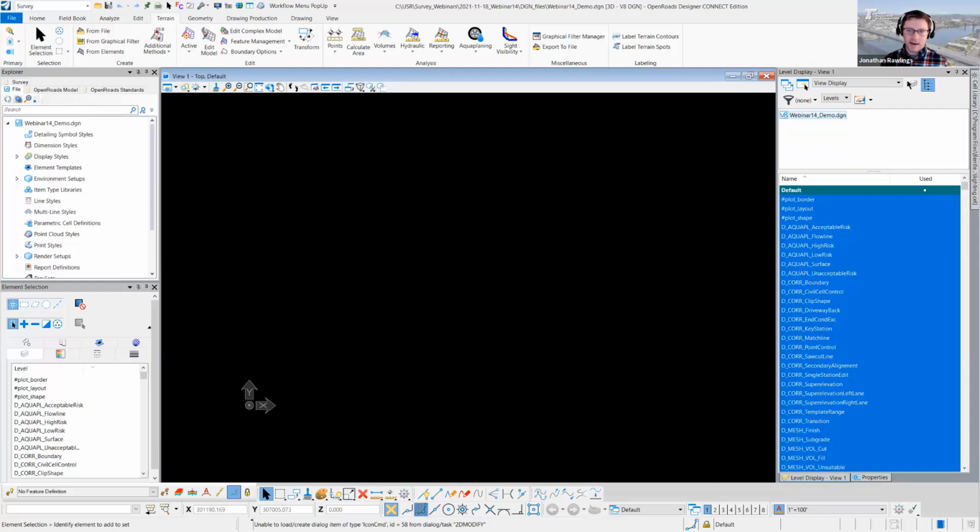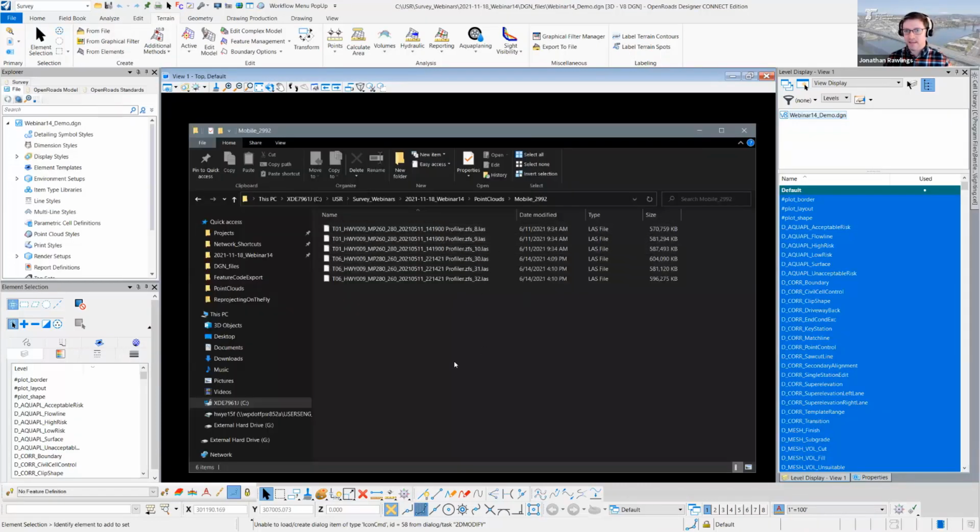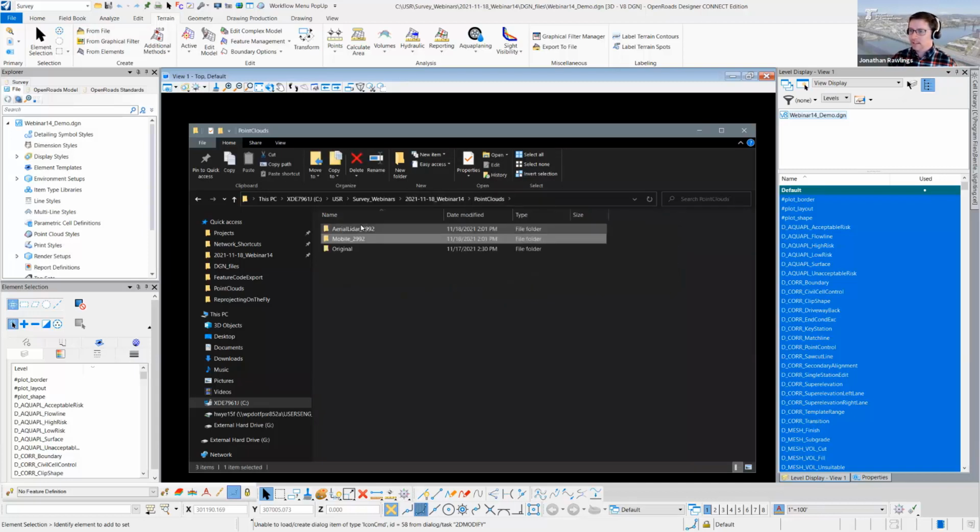So I've gone and downloaded some data over in Bandon on Highway 101 that was collected with the statewide scanning data collection this year. So I have 6 LAS files along Highway 101. These are all on the Oregon statewide Lambert projection. I've also got the aerial Lidar from DOGAMI that was collected in like 2014, I believe. That is also on the Oregon statewide Lambert projection, or 2992 for the EPSG code.